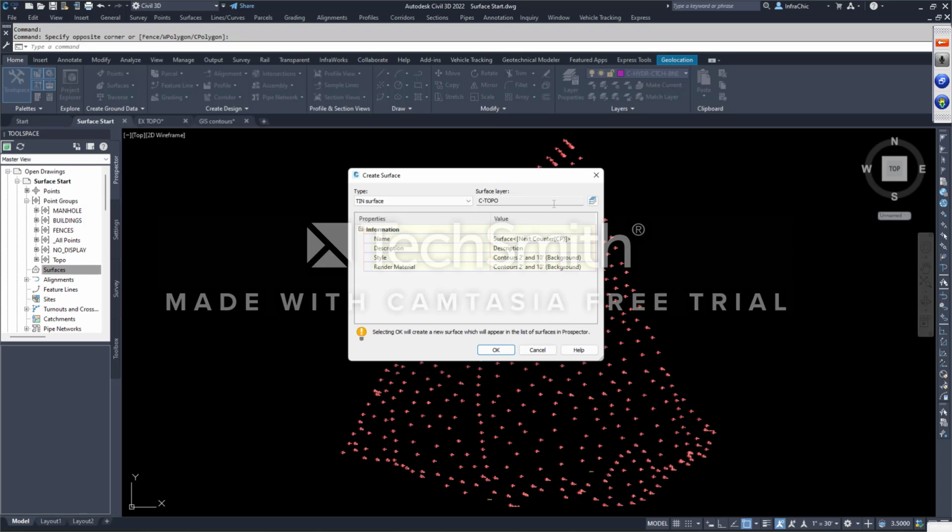You need to put the object on its own unique layer. Don't just select the layer that defaults here if it's C-topo. You need it on a unique layer because if you turn off C-topo and you have 5 different items besides that surface on C-topo, they all turn off. And that will drive you nuts. You want to just turn off the surface. You want it on its own unique layer. The object must be on its own unique layer so that it can be independently turned off and on.